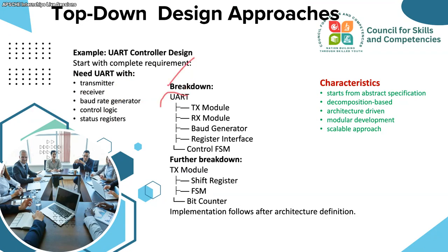This is the whole UART module, and we further subdivide it into TX module, RX module, baud rate generator, register interface, and a finite state machine controlling these modules. That is the first breakdown.